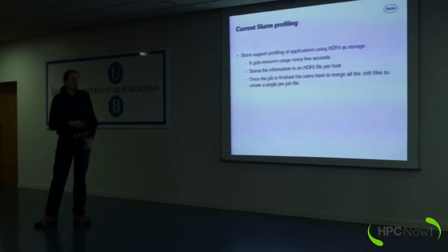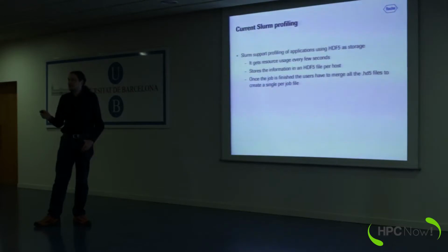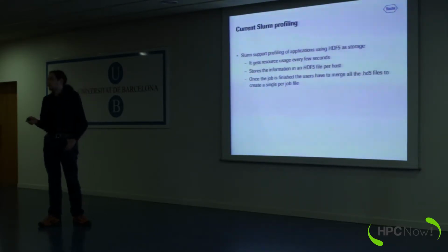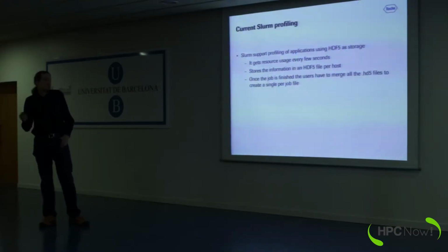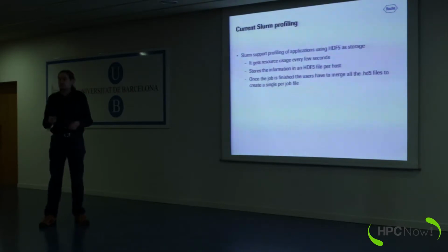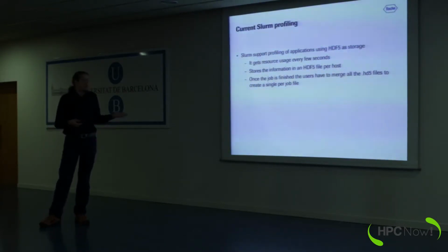The problem with the HDF5 files is that you cannot see the content until the job has finished, because they are binary files, so you have to wait until they are closed, then you have to merge them once the job has finished, and use some basic visualization tools to display the results.